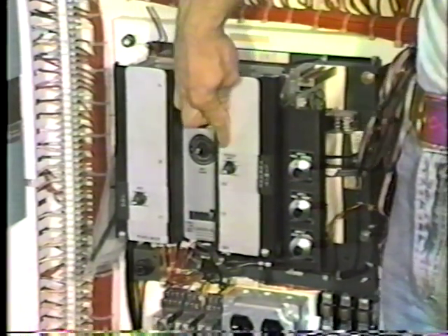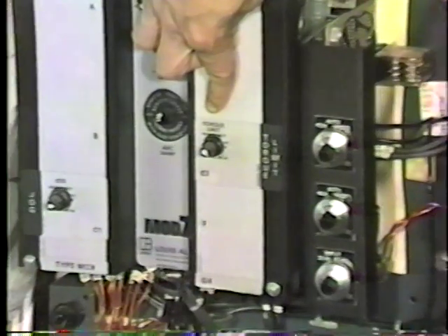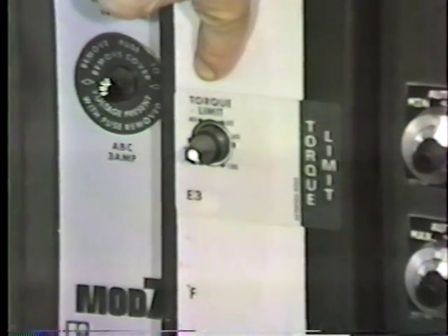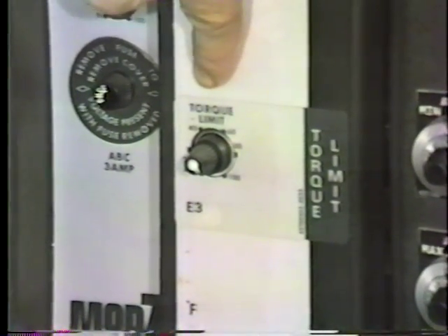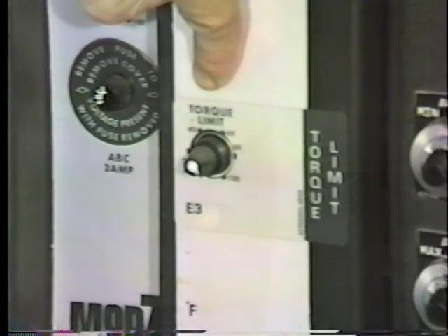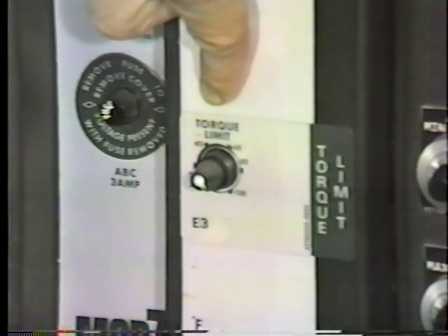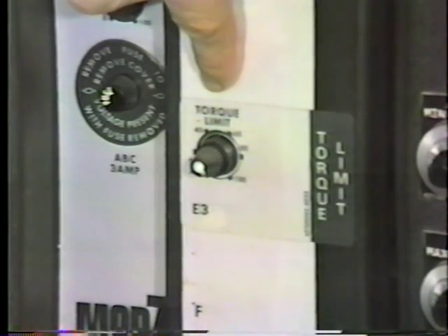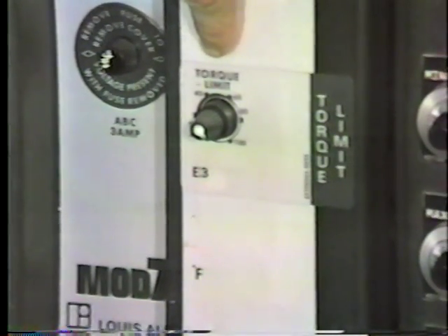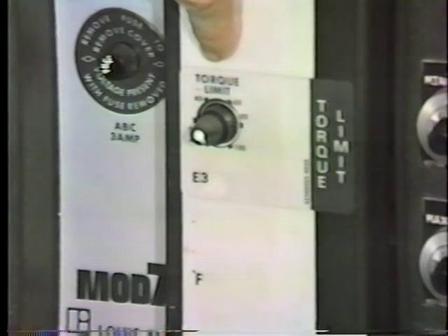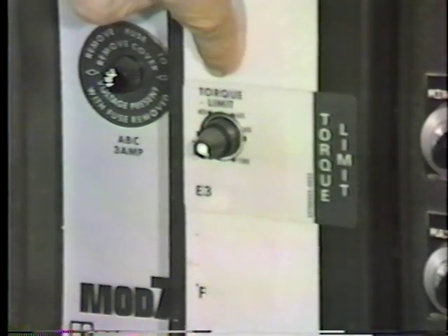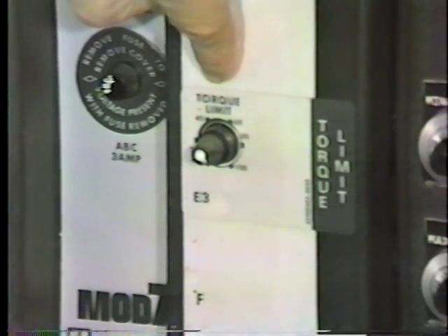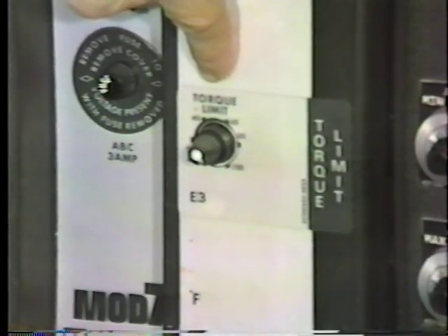We also have a torque limit. Torque limit, yes. All right. Which limits the maximum amount of current the pulverizer would handle. It would cause a slipping in the clutch. And after we get going, we can set that so in case there's a jam up inside the mill, the torque limiter will allow the mill to slip. Correct. Okay.